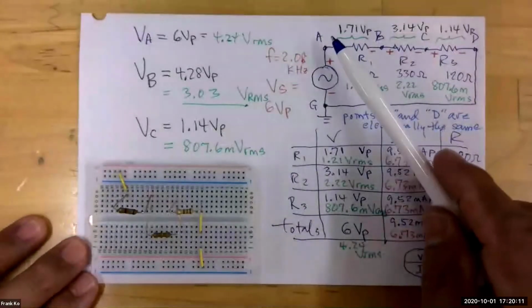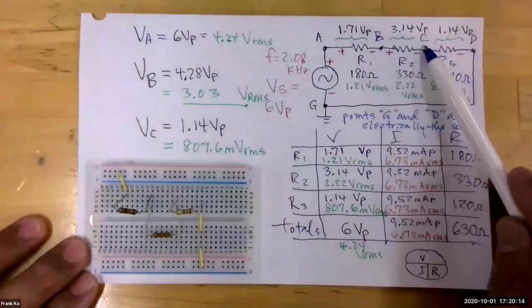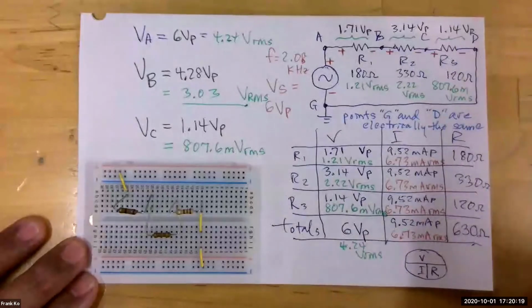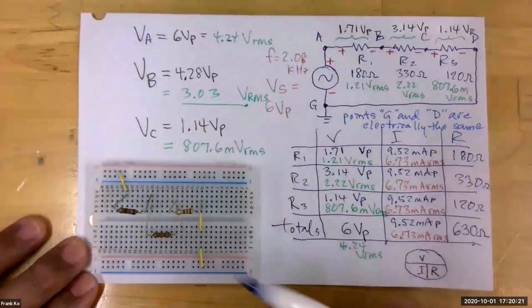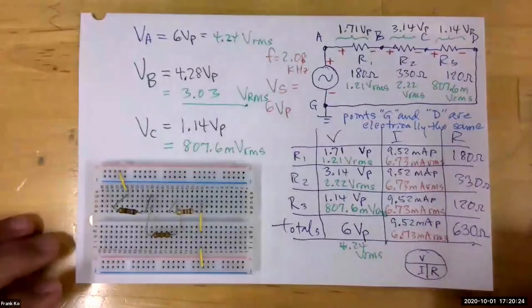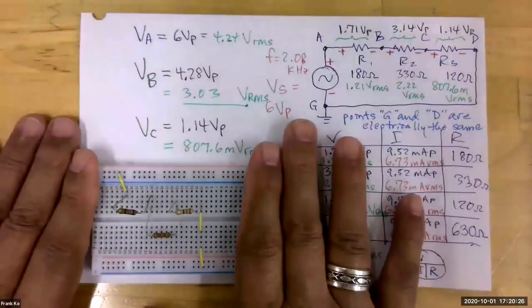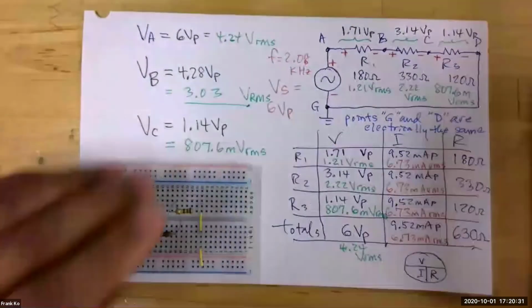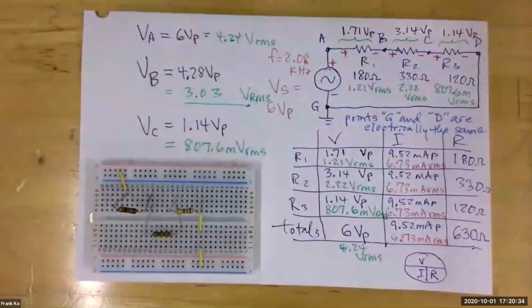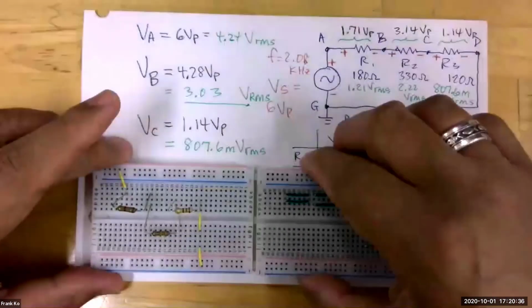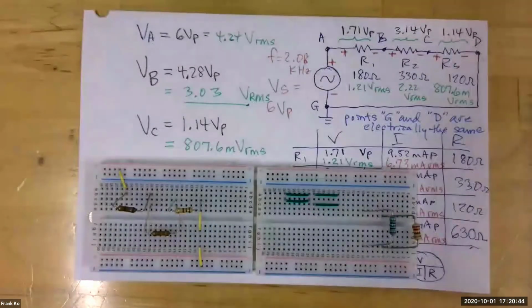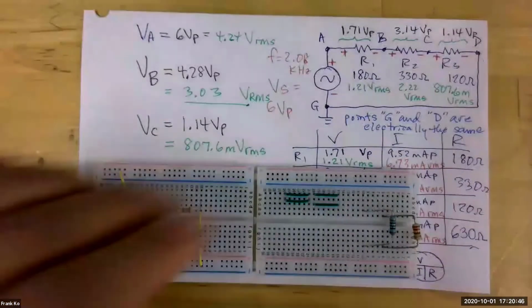We will verify using the oscope at point A, B, C, and D. And you'll be able to verify all of the waveforms that you've done in Multisim on the oscope as well. The other circuit that you're going to be building, now since I'm using half circuit boards, you can build this very compactly for half of the circuit, and then the other half of your circuit board, since you have nice long circuits, you're going to be building a parallel circuit. And your parallel circuit will look something very similar to what we've done in the past.